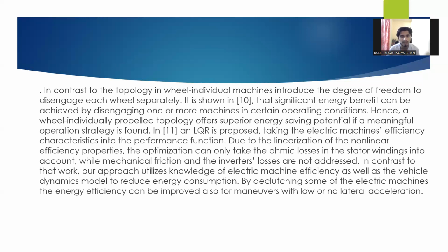Due to the linearization of the nonlinear efficiency property, the optimization can only take the ohmic losses in the stator winding into account, while mechanical friction and the inverter's losses are not addressed. In contrast to that, our approach utilizes knowledge of electric machine efficiency as well as the electric dynamic model to reduce energy consumption. By declutching some of the electric machines, their energy efficiency can be improved also for maneuvers with low or no lateral accelerations.